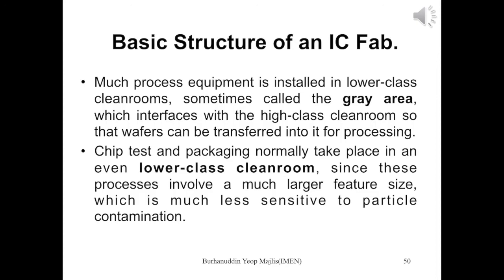So chip testing and packaging normally take place in an even lower class clean room, since this process involves a much larger feature size, which is much less sensitive to particle contamination. So it is not necessary to use the higher class clean room for testing and packaging.